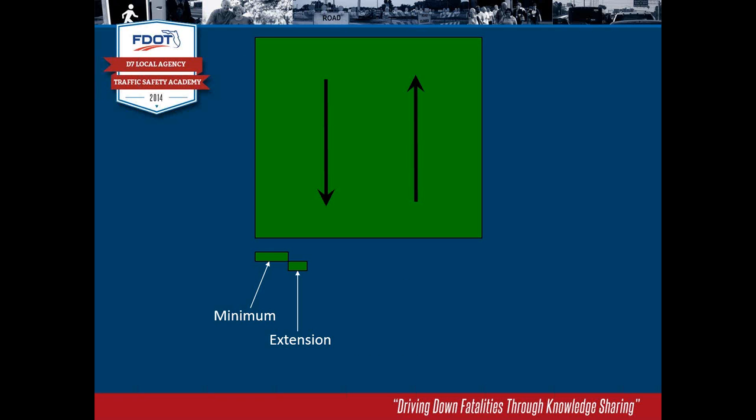Okay, when you start an actuated phase, if a vehicle has been detected, it starts a minimum time period. Typical values of the minimum are like 7 seconds. So you get a 7-second green if one vehicle is detected. Then the controller counts down the minimum: 7, 6, 5, 4, 3, 2, and so forth. When it gets to 0, typically they will then count one extension period down. So if the extension was 3, once it reaches 0 for the minimum, it goes back and starts immediately at 3 and counts down from 3, 2, 1, and so forth.